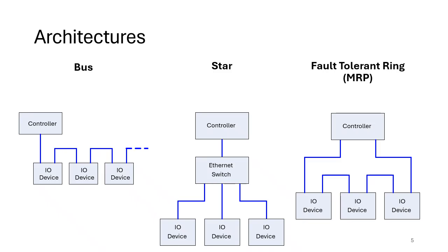So this is good because it reduces the amount of additional hardware you need, simplifies wiring, reduces panel space and so on. And the network is designed to do this. So you've got a very good architecture there with no additional hardware. Of course, there is a problem there. You have got single points of failure. If an I/O device that's in the middle or close to the controller fails, or if a cable is unplugged, then of course you do lose downstream connection, and that's where MRP comes in, and I'll come on to MRP in a minute.